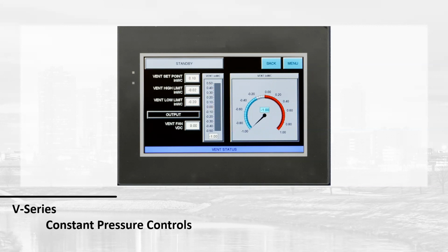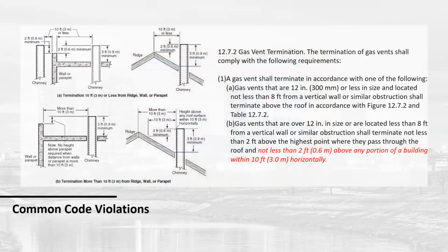So we've talked about designing around maybe boiler limitations, venting. And that's typically where we'll get the call is you're common venting 3 or 4 boilers, and the manufacturer says you can't do that naturally. So we'll get called in on that. Or we've exceeded the boiler's length on how far you can run a boiler, and we'll get called in on that. But sometimes we get called in for code violations, that the boiler can handle it, the venting system's within range, but we have certain code violations.